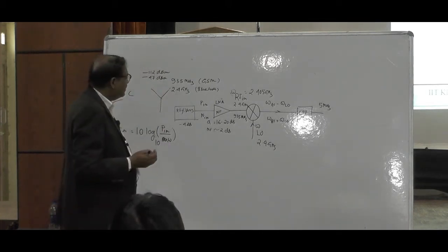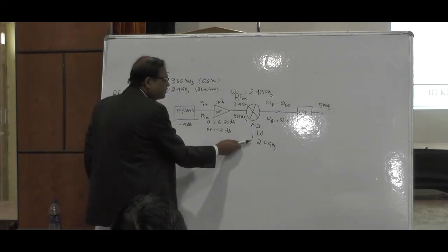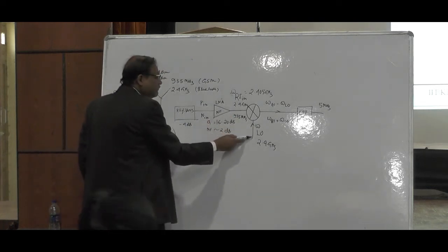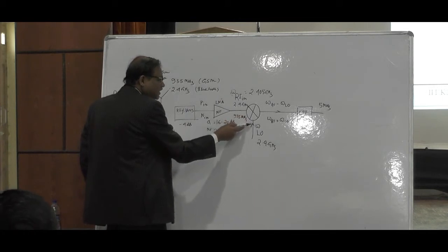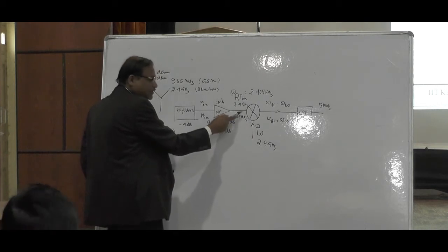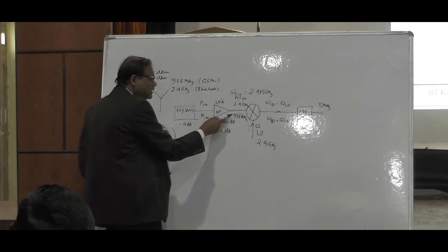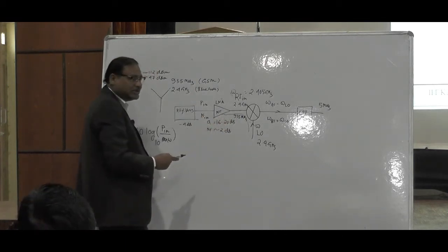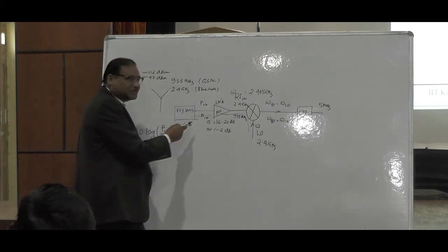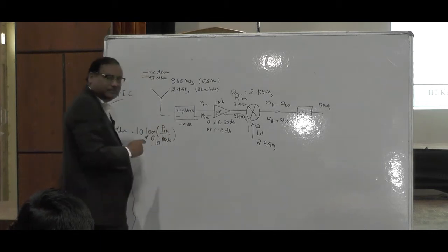Obviously things become more complicated, because suppose I am giving a 2.4 gigahertz local oscillator, right? Imagine that signal might leak through my mixer, that is called leakage. That is local oscillator to RF, so LO to RF leakage. The signal might leak through that and pass through my low noise amplifier, and then the filter, since it is a band pass filter, it will definitely pass that signal and it goes to the antenna.